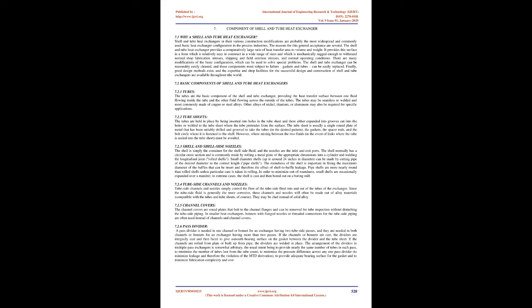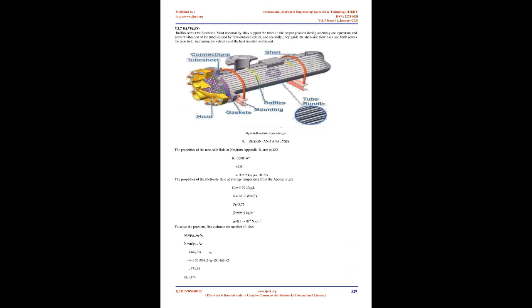The boundary conditions of the model equations are discussed in detail for the steady state, and equations of the axial temperature profiles are provided in programmable form. For the hyperbolic model, simple relationships between the model parameters are derived. Considering the transient adiabatic processes in the tube bundle, a concept for the experimental determination of the model parameter m, the third sound Mach number, is developed.